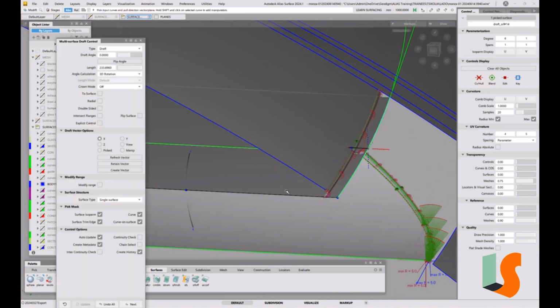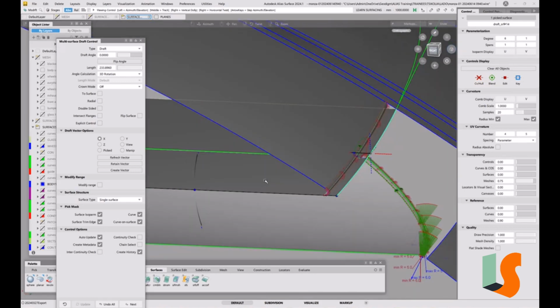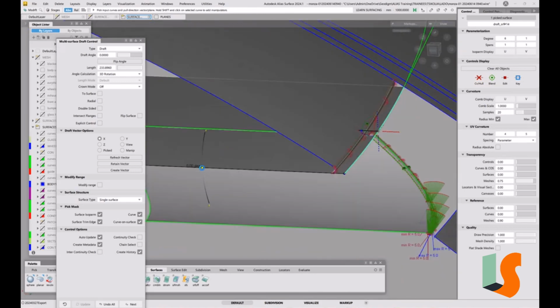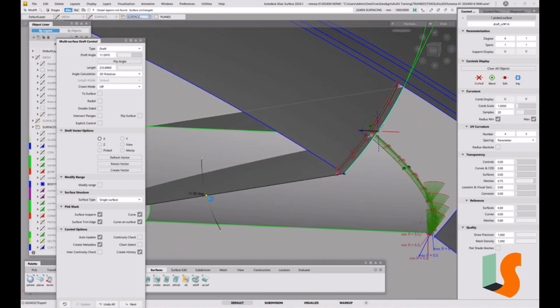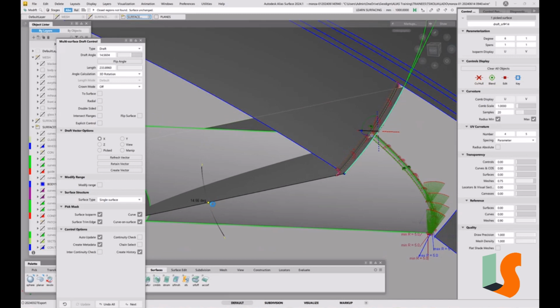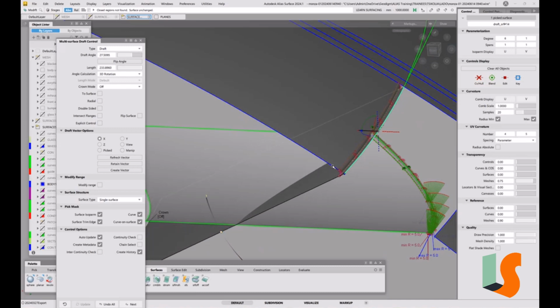So if we change that angle there, just see if we can reduce that. The other thing about changing the angle is that it will make that fillet look closer in size to this one, in terms of the chordal distance between those edges. So let's pull that down so you can see the fillet now moves towards the front edge. Now obviously if this is an intake, you don't want to close off the intake, otherwise there's no air going to go in. But now I've changed that angle substantially, so I've made it like 27.5 degrees.